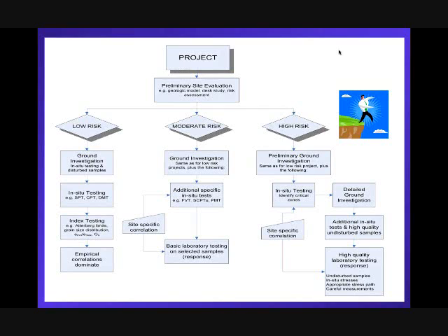But for high-risk projects, often you'll do in-situ tests, and if the ground is suitable, tests such as the CPT to get a very good handle on the stratigraphy and variability of the ground, and do preliminary estimates based on the CPT results. If there are zones that are critical for the project, often a more detailed investigation that may involve additional in-situ testing, high-quality undisturbed samples, high-quality lab testing.